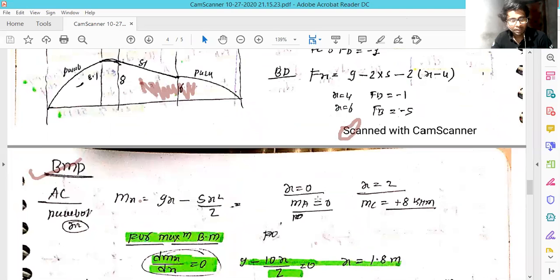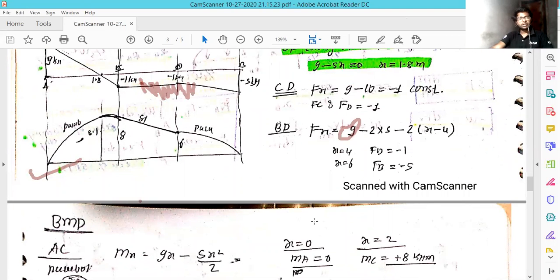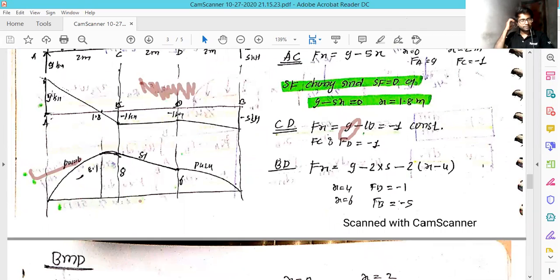Now, the below diagram you take as a notation, and I will explain afterward. If the load is uniformly distributed, we know that the shear force diagram is an inclined line, so definitely there will be a square parabola for the bending moment diagram. You can see it will vary in parabolic form for the 2 meter cross section. After that we know that there will be no shear forces, and it will be a point load kind of condition, so it only varies as an inclined line in the bending moment diagram.